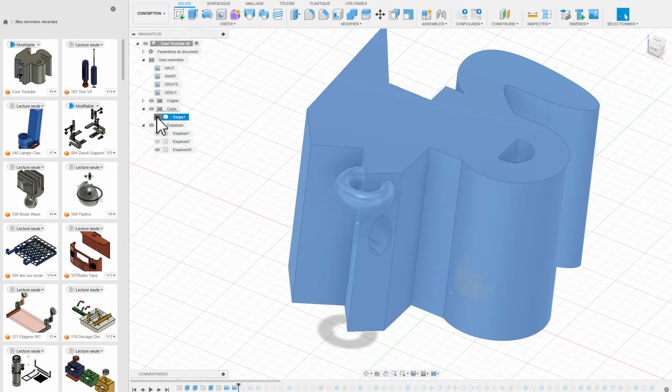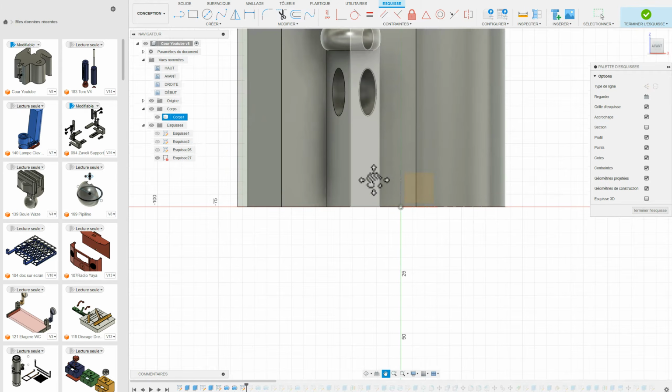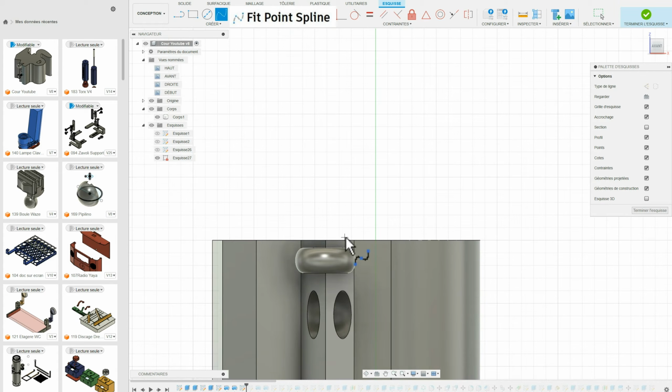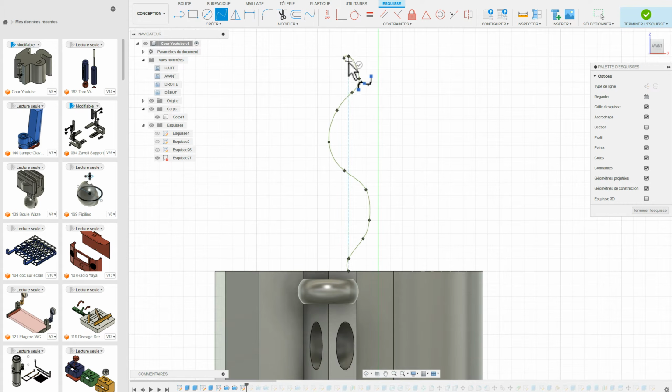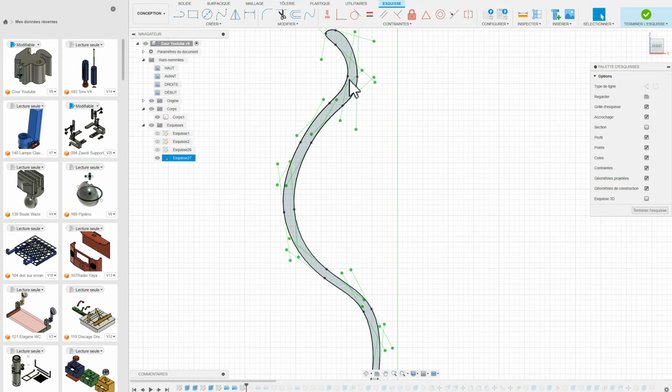Now this piece, I can hide it. I'll click on this face and make the body reappear. I move it a bit down and let's see another example of Revolve. Here with this tool I'll create a shape. I start here, let's go. I'll finish it with a straight line. It turns blue, meaning the shape is closed. I'll still modify it slightly.